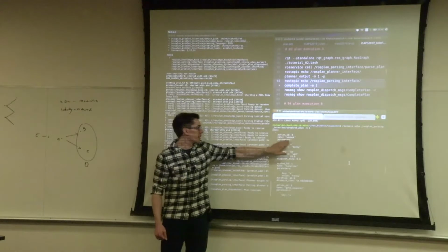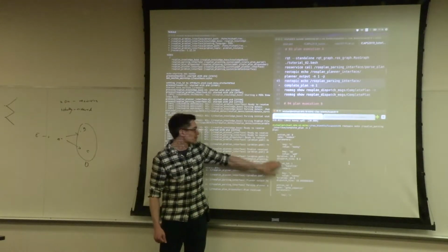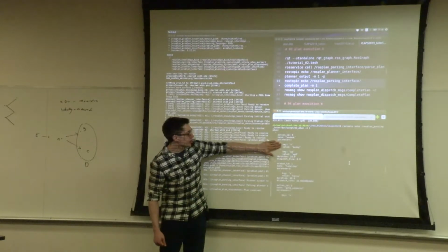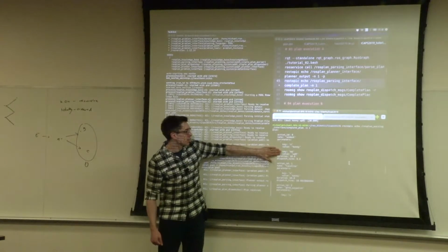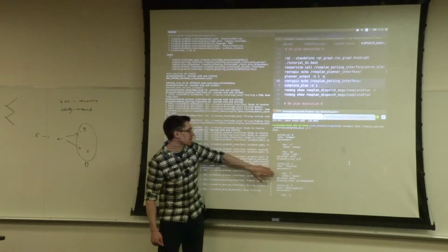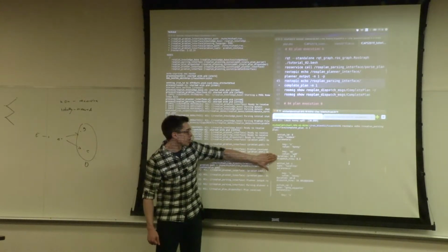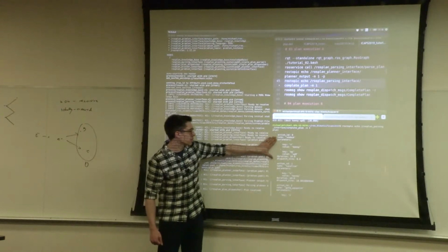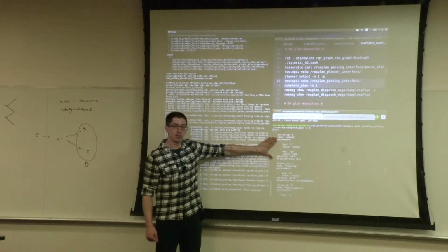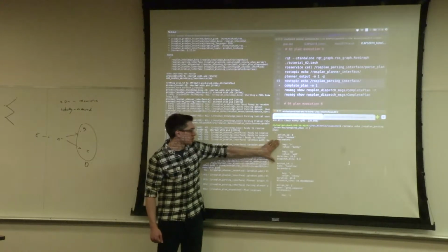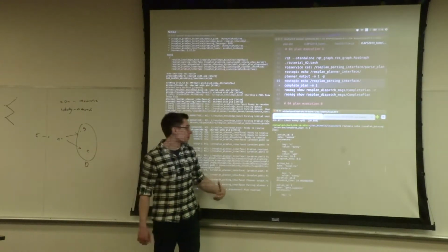The action ID, the name of the action is undock, the parameters of the action, the parameter label V is Kenny, the parameter label waypoint is waypoint 0. Then it's got this duration and dispatch time. So it's robot Kenny undocking from waypoint 0 as this action. And this corresponds to the first action in the plan that was produced by POPF.